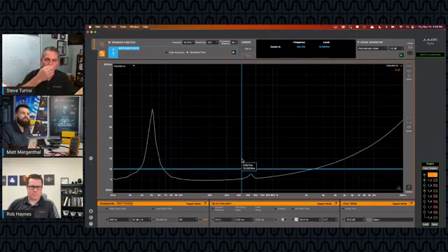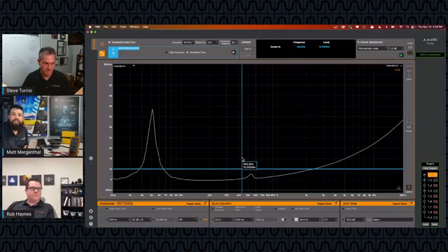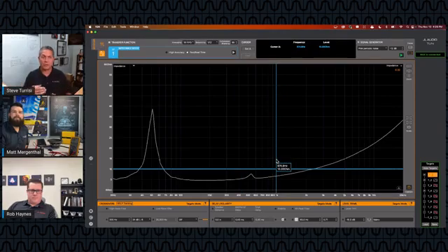Two things I want to ask about, Matt. First of all, what's that box next to your cursor, that little flag-like thing? That's a new feature that is going to be launching in our next version of Tune software, which should be available very soon. We call those data flags. It basically shares the same information that you'd see in the info box up at the top, but it puts it right where your cursor is. So if you want to see the data a little bit easier, right where your eyes are, that's there. Toggle that by hitting the F key, F for flag.